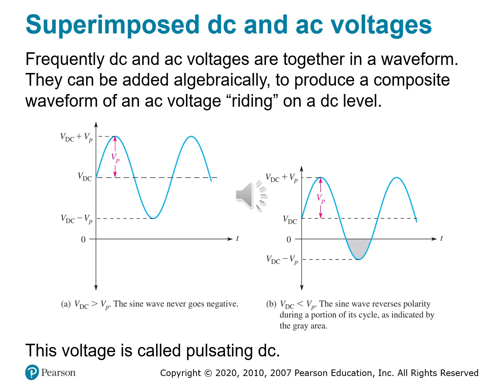This combined voltage is often referred to as a pulsating DC, especially in rectified power supplies, where the signal isn't flat, but it's also not fully alternating. This is the kind of waveform you'd see coming out of a function generator with a DC offset applied, a half-wave rectifier before filtering, or an amplifier output biased with a DC voltage. It reminds us that in electronics, waveforms are flexible, and we often add or shift them to meet the needs of the specific circuits we're working with or designing.